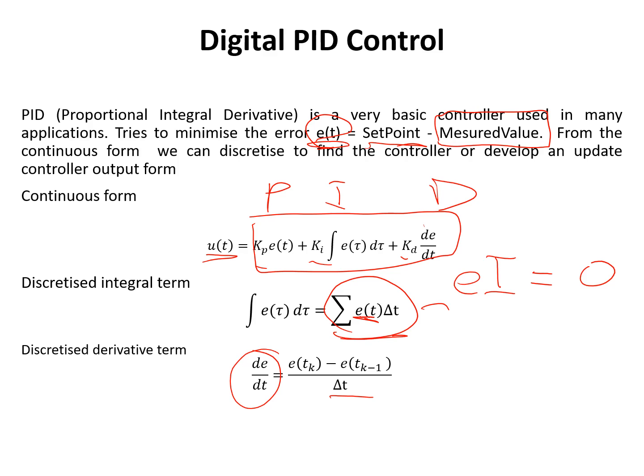For example, say we have an output which is maybe easier for now for 0 to 10 volts of our DC motor, but we have a duty cycle which is between 0 and 100%. Then we might have gains which are 10 times smaller than if we're running a system where the output is in volts. So just for example, a PID controller doesn't really care what the output is, as long as your gains are suitably chosen that the system is stable, and we get the response that you want.